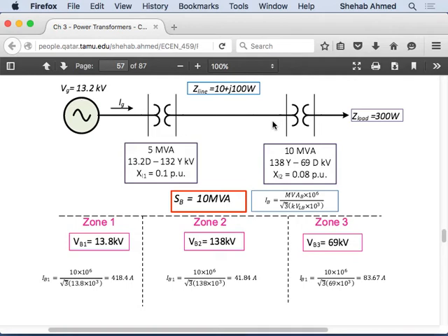If I'm talking about designing of a protection system, I care, because the angles between the voltages and currents are very important. Anytime instantaneously I have two voltages that are not in phase, current will flow between them. If I have two nodes with voltages that are not in phase, then current will flow between the two nodes, right? So for protection purposes, I need to consider that, and I cannot put two transformers in parallel that have different phase shifts, because there will be circulating current between them, right? It's like two different voltage sources, right? So from a protection perspective, it's a good point.